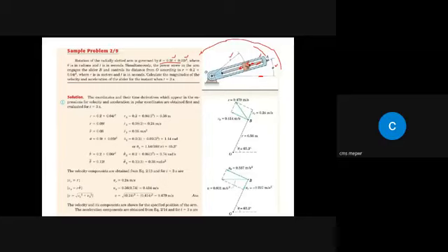So r is given by this equation. At t equal to 0, r is given as 0.2. Put t equal to 1 and you will get the r value. Similarly, at some other time you put that value of time and you will get your required r value. Is it clear? Yes, sir. Okay, where r is in meters and t is in seconds, calculate the magnitude of velocity and acceleration of the slider, meaning this object, when t is equal to 3 seconds, right?